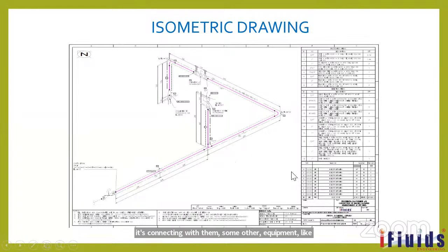So in fabrication there is the BOM. In some table they will mention the fabrication details, like for a 1 inch pipeline, how much length has to be cut. Here it is showing a center distance. If you see this drawing now, here they are showing from this weld joint to the center of the T, 529 mm.